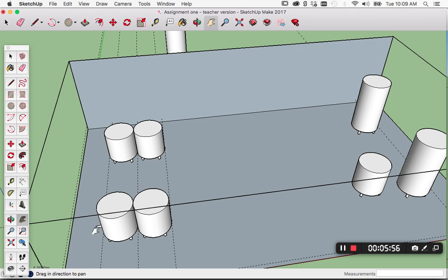So if we look at the fixed line option, the static head, that vertical distance, isn't going to change in any way due to the height of the liquid in the tank, because we're discharging liquid into the top of the tank. So it doesn't matter if that tank's empty or full, the liquid still has to get all the way above it. So the maximum static head for the fixed line option would be when the liquid is at the lowest point in one of these tanks at the bottom, and then is being sent over the top.